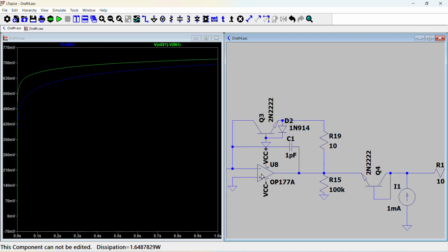So because of parasitics, the signal will come closer and closer to a 180-degree inversion when the frequency of small signal inputs increases. So when there's noise in the circuit, it can come to a situation where the feedback is above 1, but also it's inverted 180, so it actually ends up adding to the input instead of subtracting.